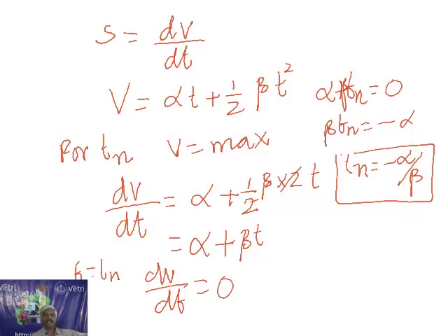That means Ti equals 2 times Tn if Tc equals 0, or Ti equals 2 times Tn minus Tc if the temperature of the cold junction value is given. Substitute this and we can find it. So this is the thing we have to understand.